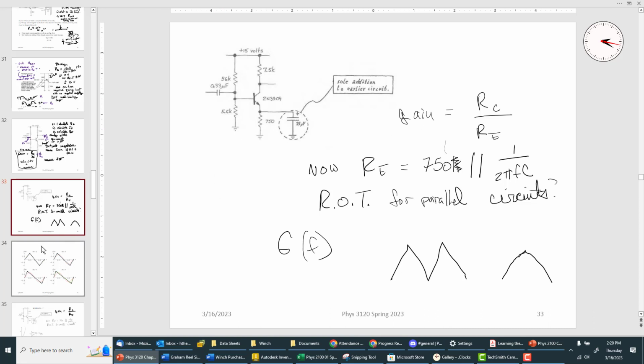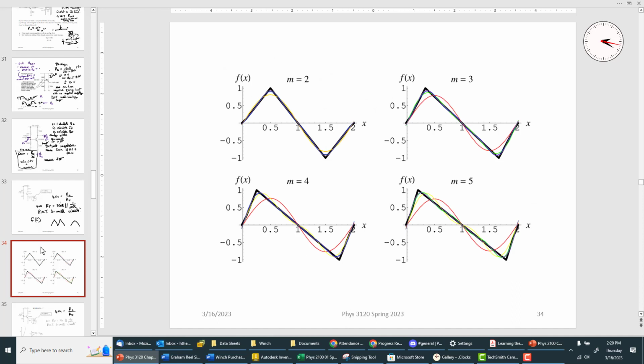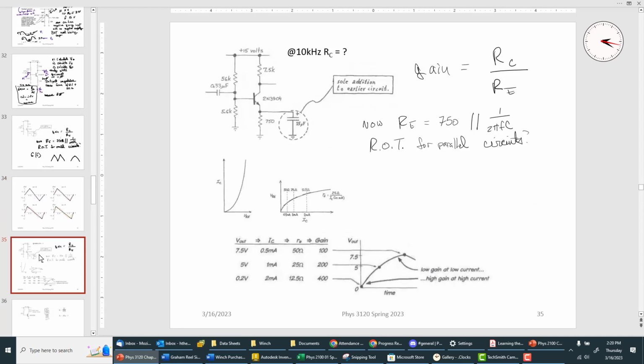And so armed with this little bit of information, you can calculate what is the Z, or simply what is the resistance of the capacitor at 1 over 2 pi times 10 times 10 to the third times 15 times 10 to the minus 6.